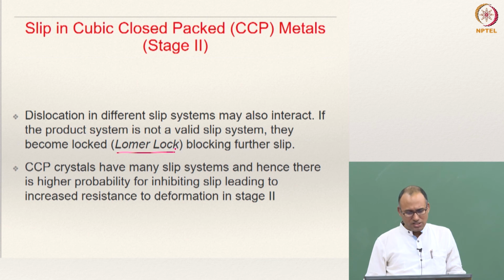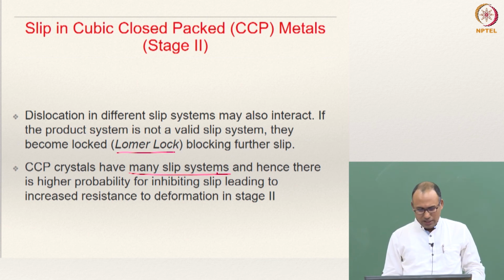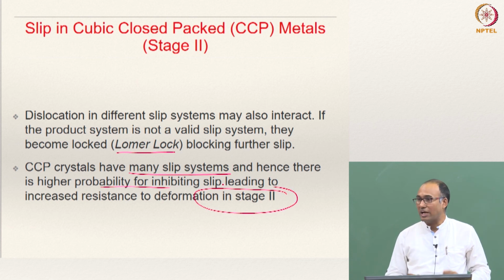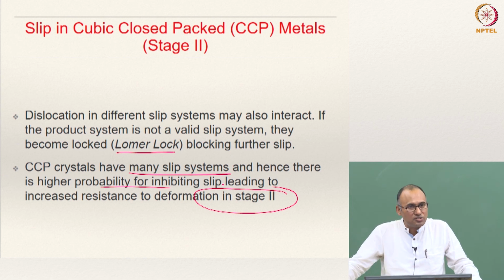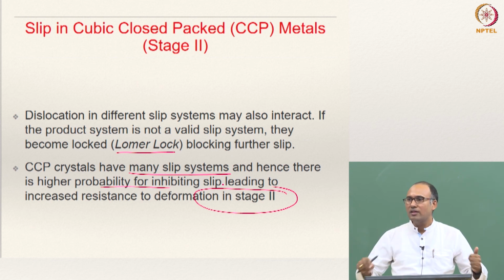And cubic crystals have many slip systems, as we have discussed, and hence typically they have a very high probability of inhibiting slip, leading to the stage 2 deformation. That is why stage 2 is characteristic of cubic single crystals, wherein the dislocations interact with each other and cause work hardening.